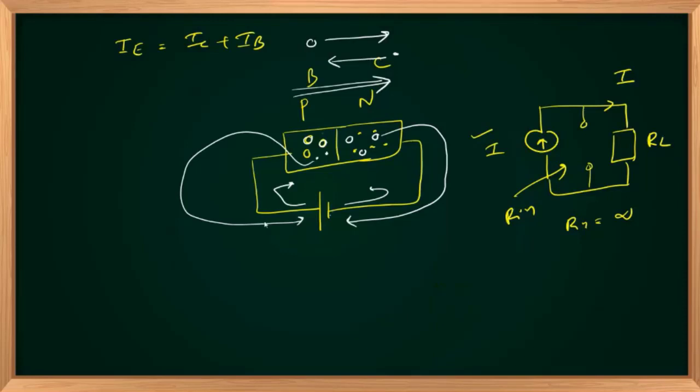Or the other way, for a forward biased PN junction, you can expect a one word question from this. A forward biased PN junction will easily cross, or the forward biased PN junction will help the majority carriers to cross the junction, and the same forward biased junction will block the flow of minority carriers. Is it correct? Clear? Holes are repelled by the positive pole here, cross, attracted by negative pole. Electrons are repelled by negative pole. Majority of electrons are collected by the positive pole.